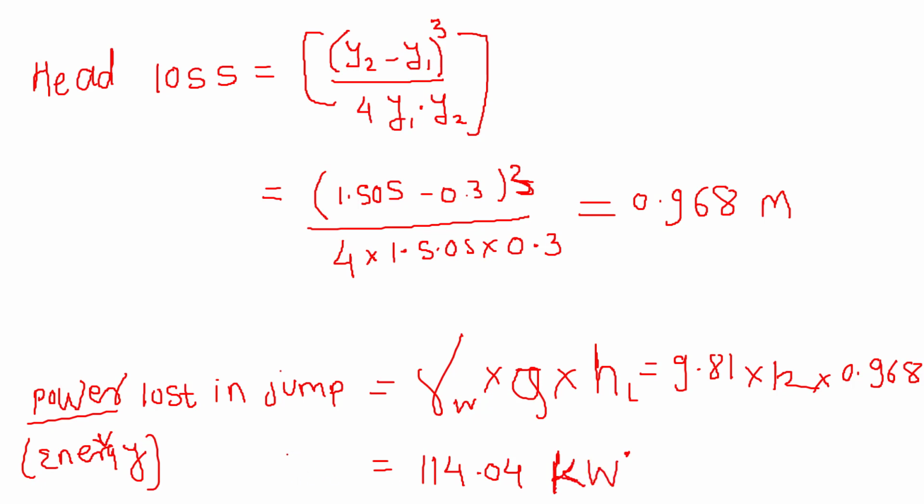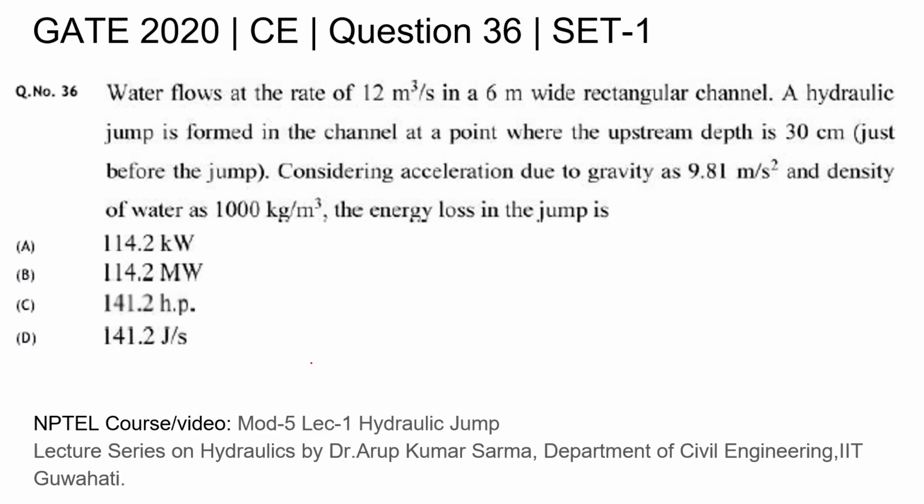This is our answer, energy loss, right? So remember the unit of the specific weight, the unit of the discharge, and the unit of the head loss, right? Finding our answer in the options, it will be 114.04 kilowatt. The answer will be option A.